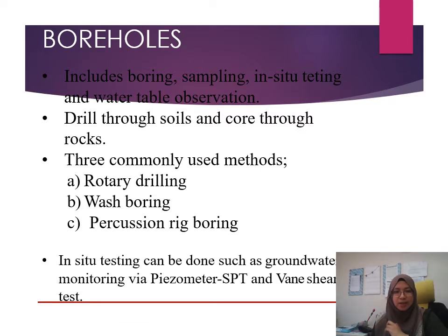Next is borehole. It includes boring, sampling, in situ testing, and also water table observation. In the borehole, you have to drill through soil and core through rock. If your site involves soil only, you drill inside the soil. If it has rock, you have to core into the rock. So the cutter bit will be different for soil and rock.